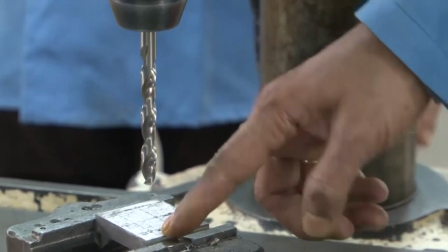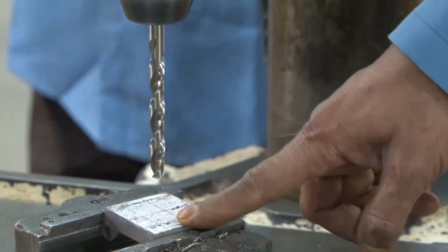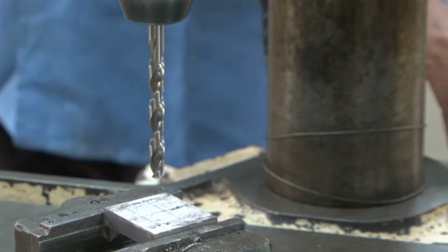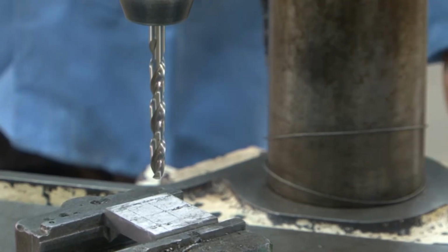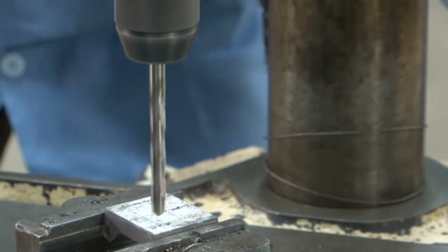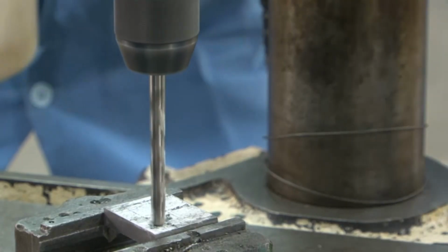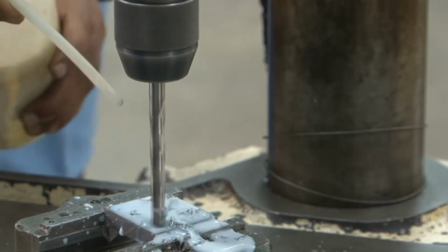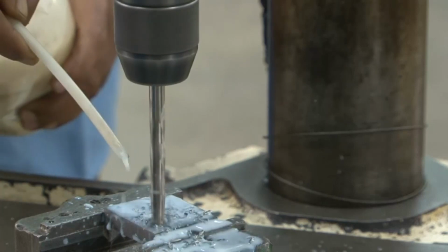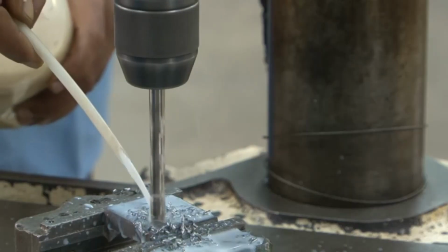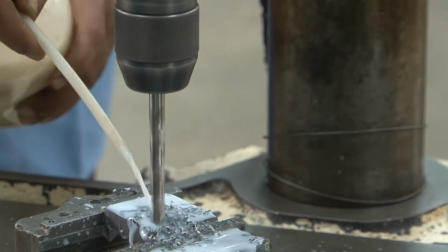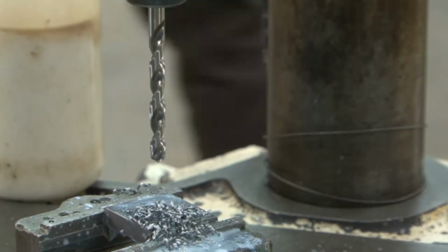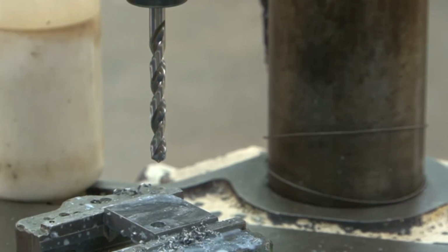Then there will be reaming done, then there will be tapping done, and finally, the hole will be a metric hole, M10. That is how it is written on the drawing, the hole as M10, which is metric, and the 10 millimeter diameter. The drill is switched on. Since the marking is already there for the center, at that center the drill is touched first, and then it is given the downward movement for penetrating the workpiece, and the hole will be a through hole. And then the drill is taken out, it is switched off. So, one hole has been drilled, and then the next hole has to be drilled.